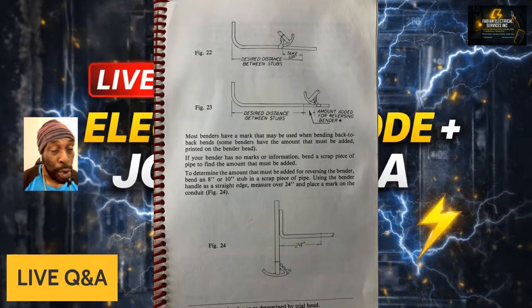So that's how you normally do your back-to-back 90s, or you do your take-up. Again, these are different techniques I've learned on the job site throughout my years. If I do a back-to-back 90, I can make my first bend at 90, and my second bend, I can hit it on the star and make my bend, or I can do my measurements. It all depends on what you've learned and what you've done on the job.